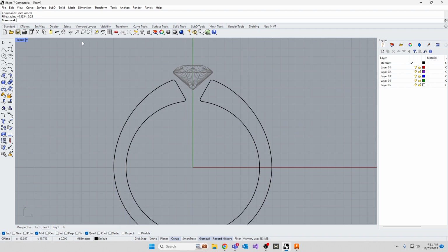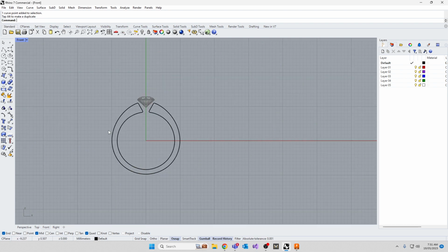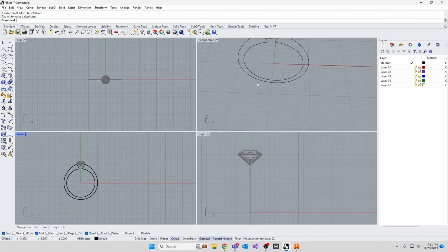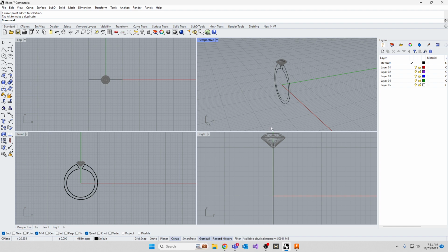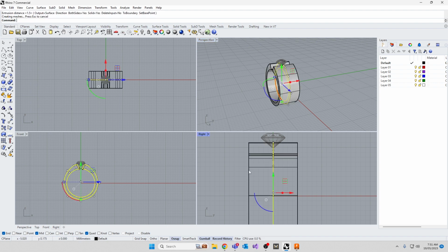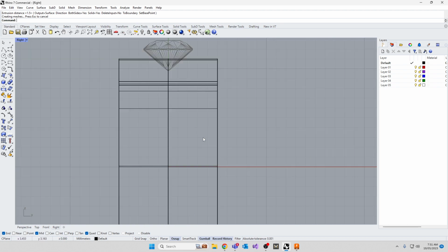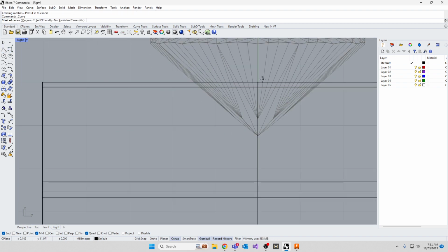So let's talk about the many ways we get to do this. I want to bring that bottom one just in a little bit. Looks a bit fat. You can extrude, would be the one way, and you can do a Boolean, an inverse Boolean. So let's take this guy. Let's extrude it in both directions. Now let's draw another curve in the side view, like so. We want to come from you, we want to come out like that.